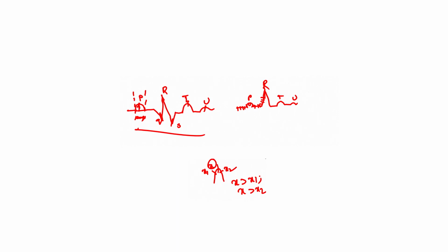If I do that in an algorithm, I can easily find out how many peaks I have in the ECG signal. In this case we have P one peak, R one peak, T one more peak and U one more peak, but I require only the R peak. But how do I differentiate which is the P peak, R peak, T peak and U peak? It is very hard to differentiate, but if I can pass only the peak of R, neglecting the other peaks, I can get only the R peak, and if I count how many R peaks I get with respect to 1 minute, I can easily calculate BPM.